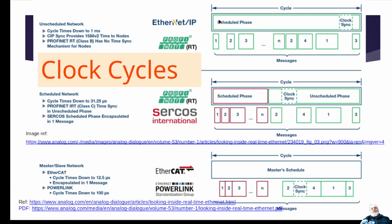Then what you want to do is send different data. Let's say we're sending data from our PLC to 3 different robots, telling them how fast to go. Spot 1 will be the speed for robot 1, spot 2 is for robot 2, and spot 3 is for the third robot. We lay out all the information and send it out every millisecond. Every millisecond we send the robot speed updates. It might be the same speed as last millisecond, or we might say speed up a little bit or slow down a little bit. That's the scheduled phase of data that we're sending.